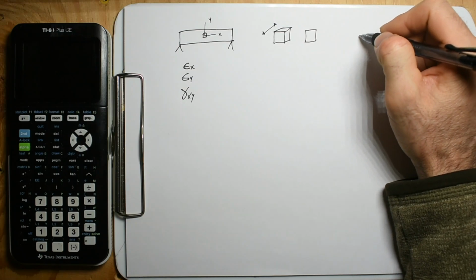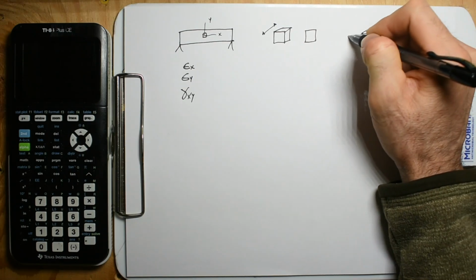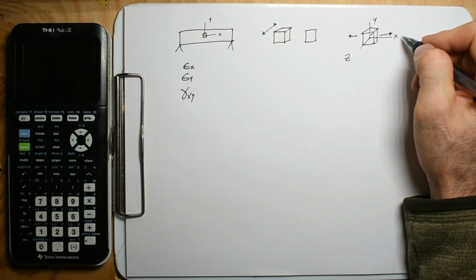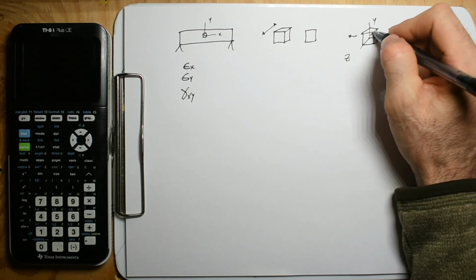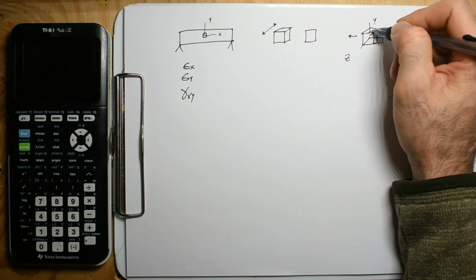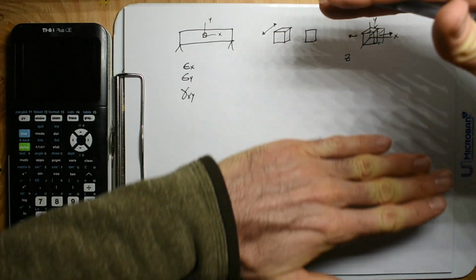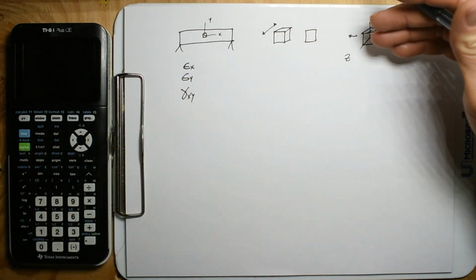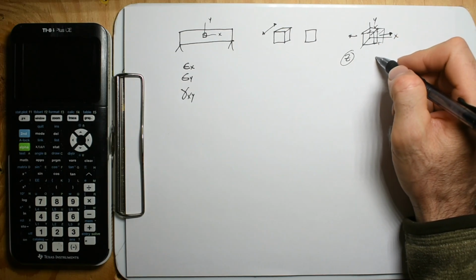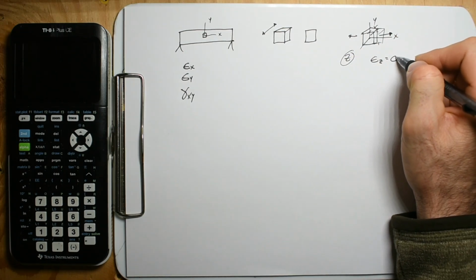If I have this cube and I'm putting it in tension, this is the x, y, and this is the z plane. Sure, it's going to lengthen, but it's also going to squat. It's going to compress in this direction and this direction, so it's going to narrow in this z direction. But for these problems, we have to be very specific and say it's not doing that.